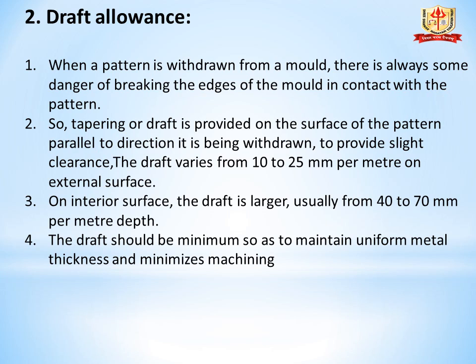Point number 3, on interior surfaces, the draft is larger, usually from 40 to 70 mm per meter depth. Point number 4, the draft should be minimum so as to maintain uniform metal thickness and minimize the machining.